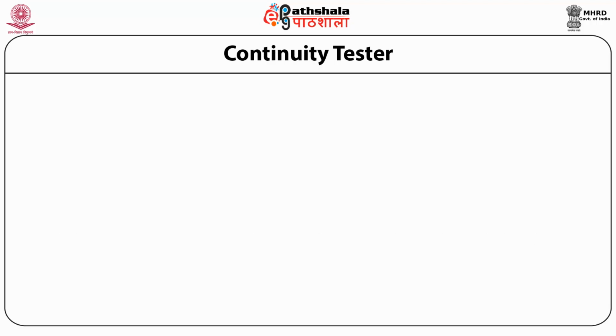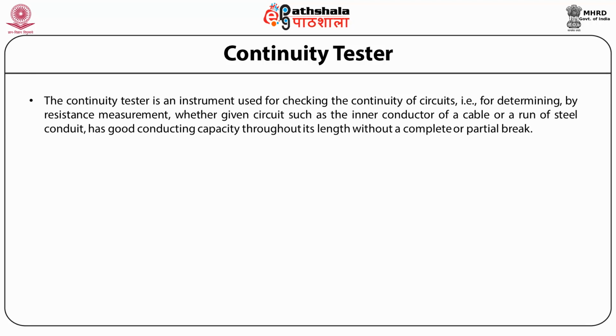Students, at the end, let us see the continuity tester. The continuity tester is an instrument used for checking the continuity of circuits, that is, for determining by resistance measurement whether a given circuit, such as the inner conductor of a cable or a run of steel conduit, has good conducting capacity throughout its length without a complete or partial break.